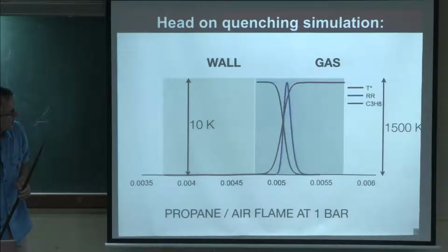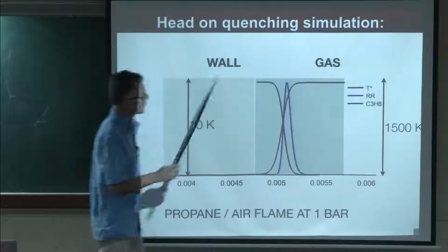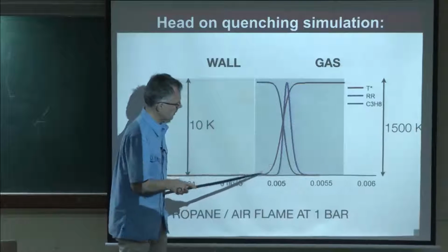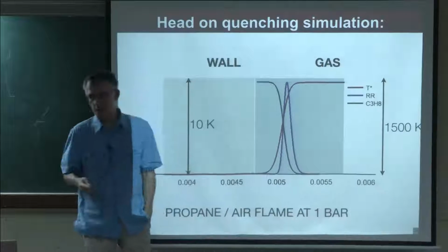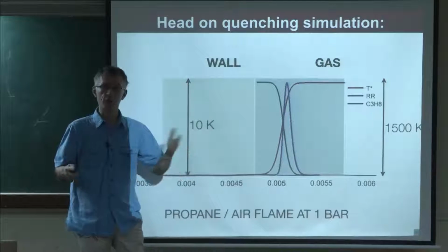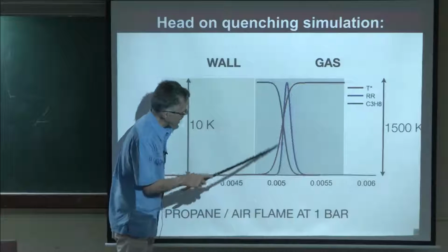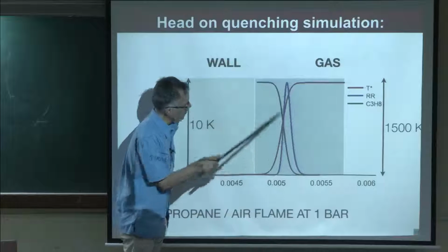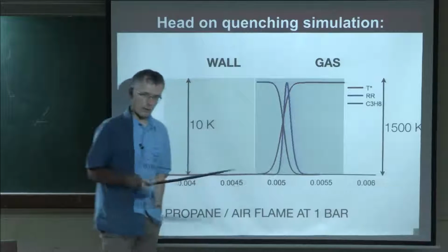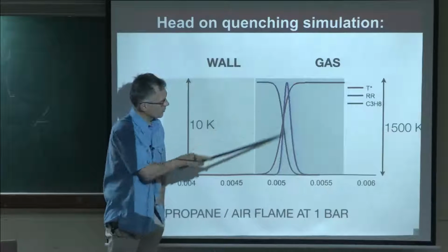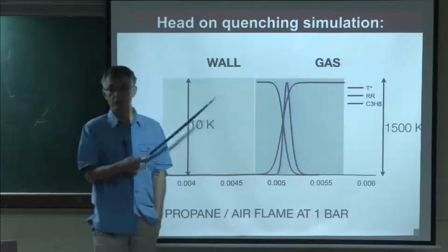So let me show you again this movie. So we have here the things we're going to discuss later. This is temperature. This thing is moving at the displacement speed or at the consumption speed. Here it's the same because this is a 1D flame. This is the fuel mass fraction in black. And in blue, you have the reaction rate. So now, when I'm going to play this thing again, you will see the flame coming here. The reaction rate will go to 0 when the flame quenches.